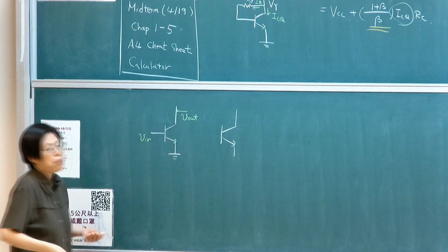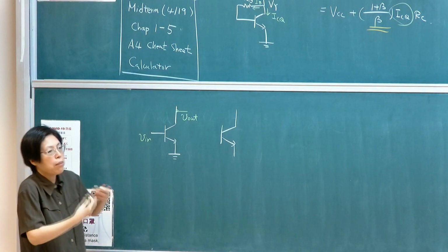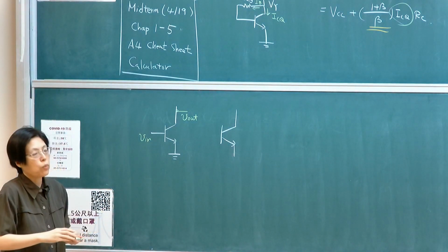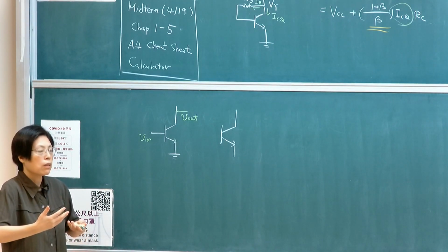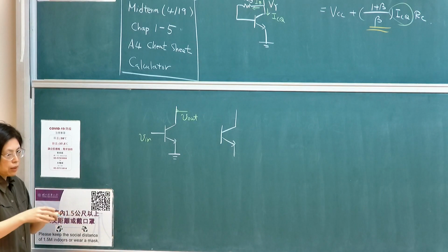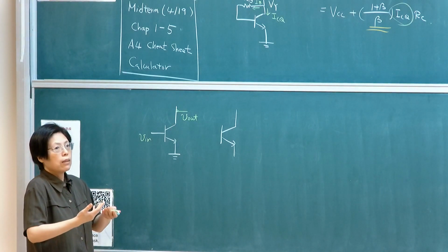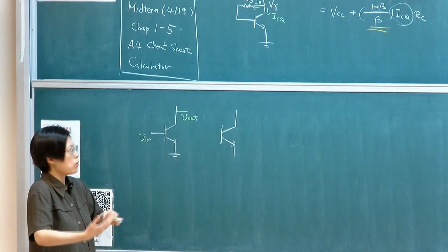the collector is typically the output terminal for most of the voltage amplification. We're going to explain that a little more, because for voltage amplification, what we typically want is to have high output resistance in order to provide gain. Remember, the gain depends on current modulation, and then you transfer this current into voltage.